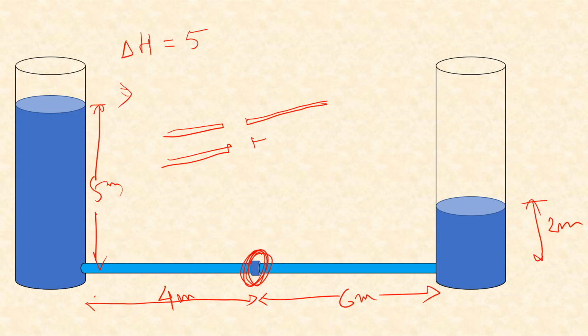I'm just drawing the longitudinal sections of the pipe, and these pipes are now joined by another socket, and so there will be this kind of irregularities here where some extra turbulence will be taking place, and because of that also some more head will be lost.